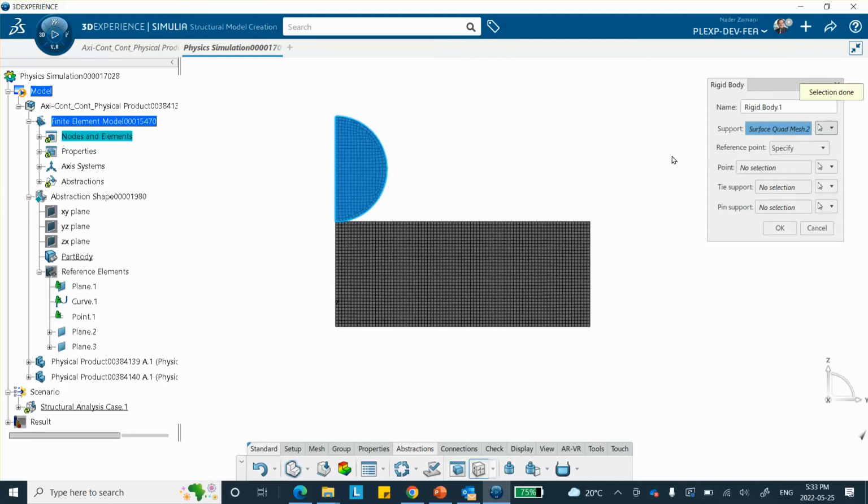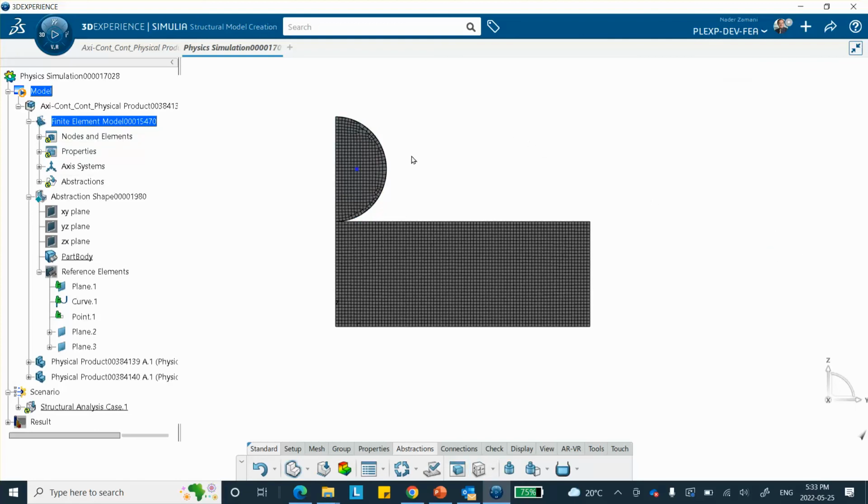Although I put a material on it, I understand, but it says, where is the reference point? I think in that video tutorial on ABAQUS CAE, the guy is using the reference point up here, but I'm going to say, okay, you put it at the center of mass of it. So there are some differences in the way I'm doing it and the way he has done it. And then that's it. It's going to create a reference point, and you can see it's right there, okay? Now we go to where I was, scenario.